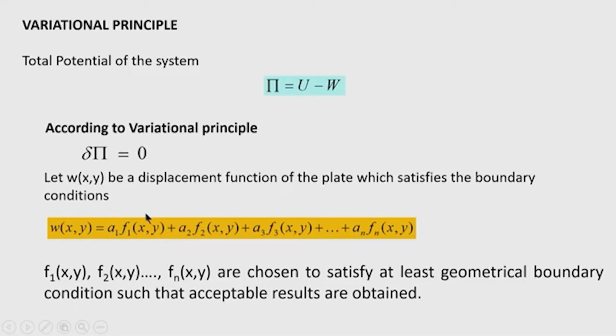So, the eigenfunction for a simply supported beam is very simple in nature, but it is not so if I take a cantilever beam. For a cantilever beam, the eigenfunctions are complicated, consisting of cosine hyperbolic and sine hyperbolic functions as well as trigonometric functions. How the eigenfunctions are found out, that is another question. Eigenfunctions are found out from the solution of the free vibration equation.